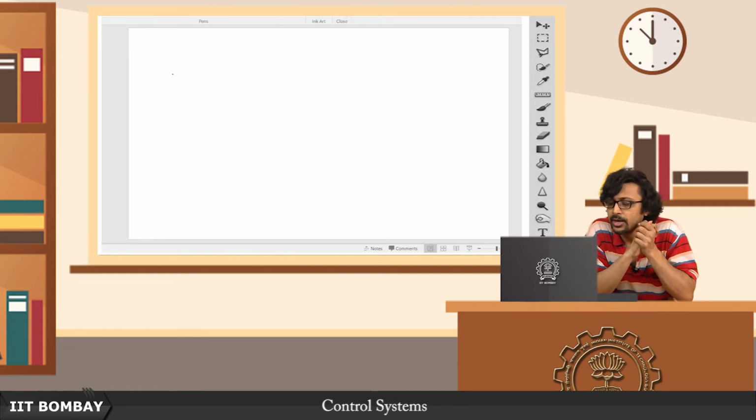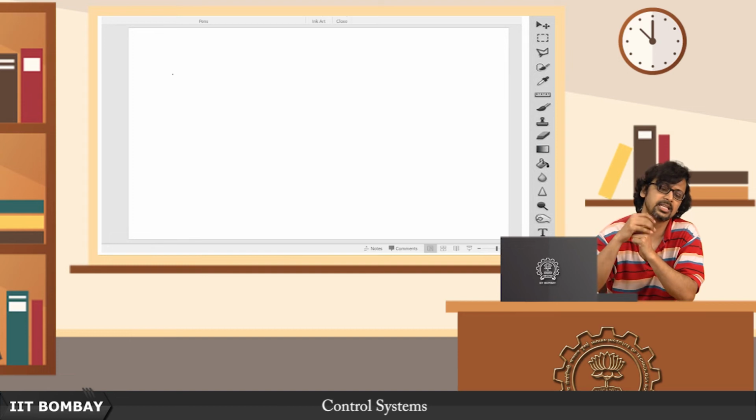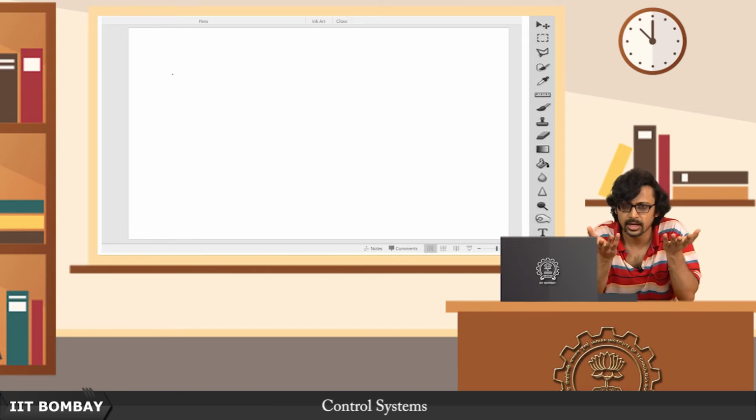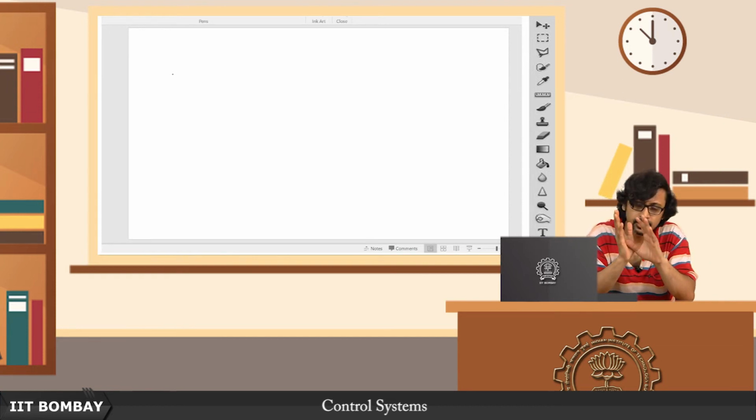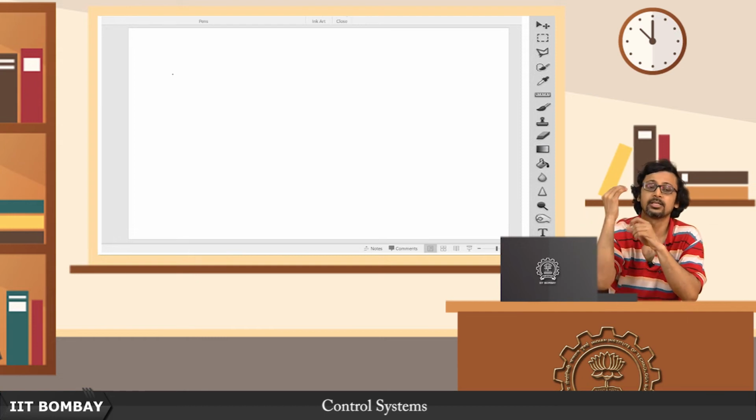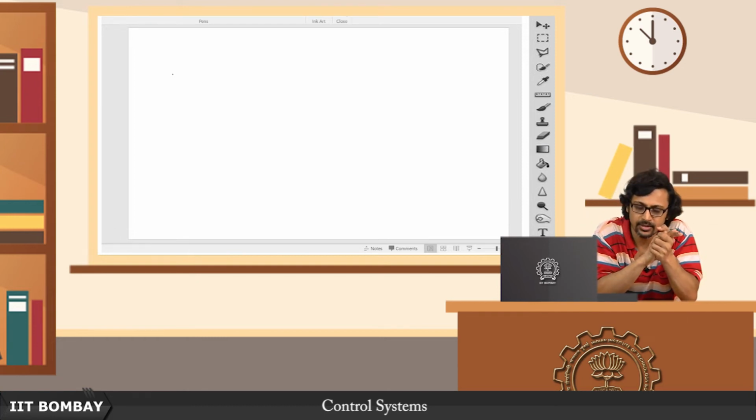Standing assumption is we are only going to be looking at stable systems which eventually acquire some steady state value. You see, if systems are unstable, they do not acquire any steady value, the system responses blow up, they are unstable, we have seen that, right, in an earlier lecture. So in summary, the assumption is going to be thus: all the poles of the system are going to be on the open left half plane, or at best on the imaginary axis, but not repeated, okay. So that is the kind of systems we are going to have under consideration, and subject to that we are now going to look at the transient responses.